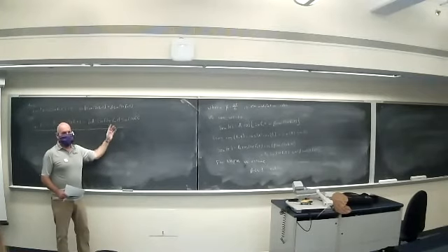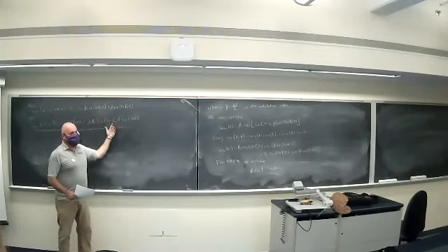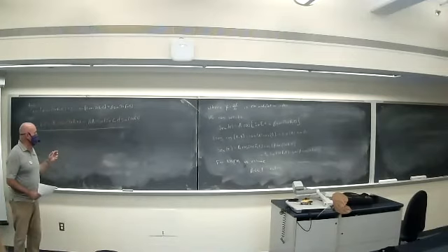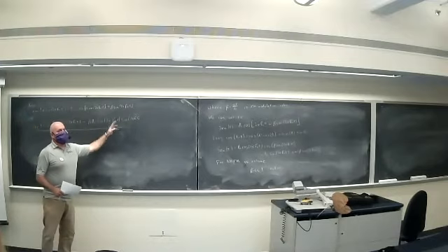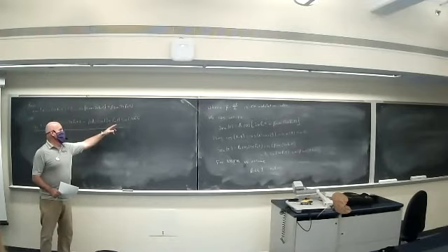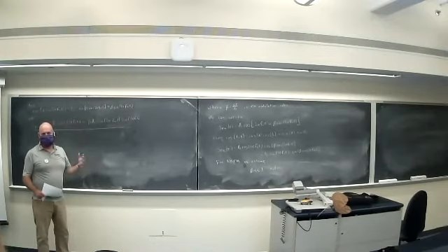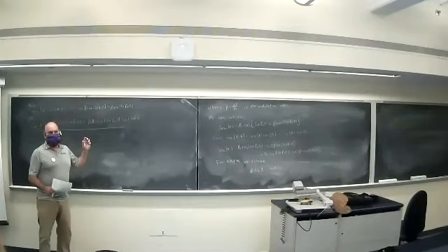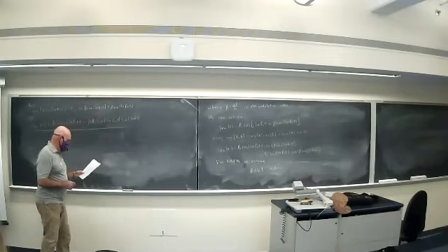And 2 cosines gives us the sum and difference frequencies. Sines are just 90-degree phase shifted cosines, okay? Product of 2 sines gives us exactly the same result. We'll get sum and difference frequencies there. So we have an impulse at fc, and then impulses on either side of that at fc minus fm and fc plus fm. That's AM radio, okay, essentially. It's different, but it has impulses at the same locations as AM radio. Okay.